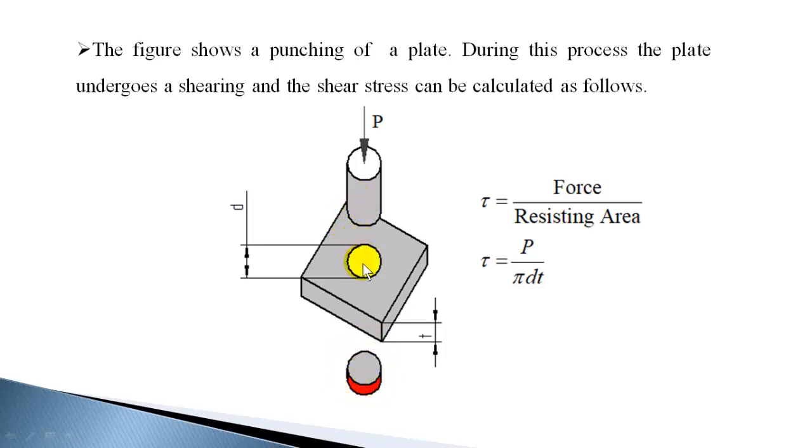The force is applied, so this inside area, which I have not shown here, you cannot see here, but this removed portion you can see, this red colored portion, that is the inside area which would have resisted the applied force. This area is lying in the vertical plane, and the force is also vertical, and both the area, resisting area and force are parallel, and the corresponding stress induced is shear stress.